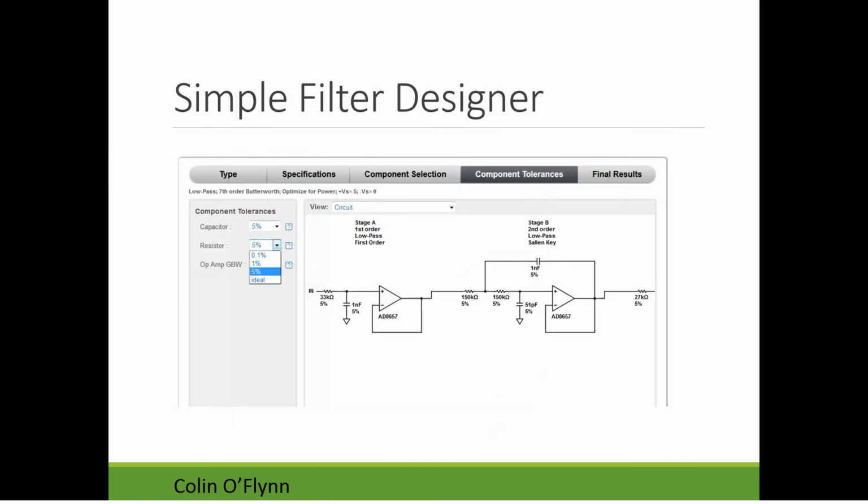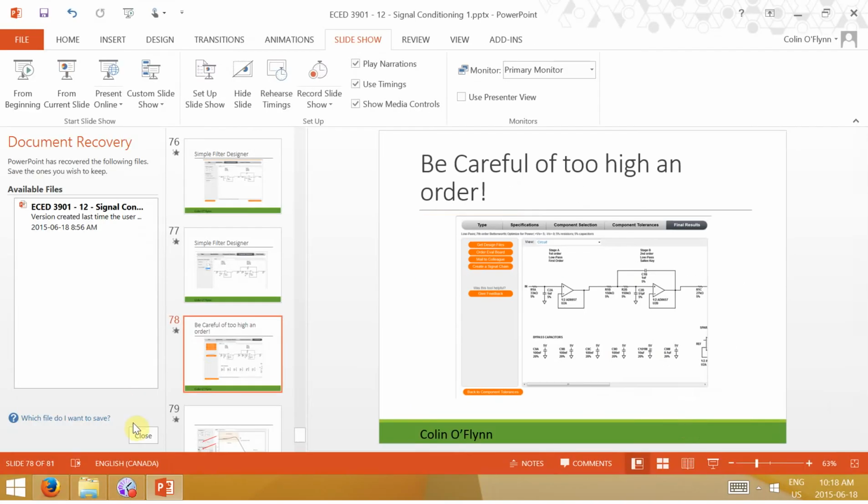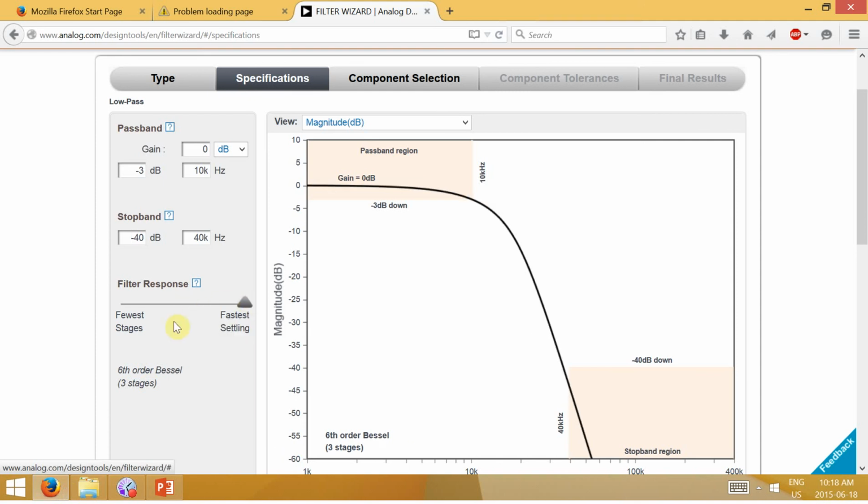The only thing to watch out for, and it'll also do this issue where you have to assign correct values to the resistor and replot, possible values to the resistor. The only issue is that, if I give it a really tricky design, it'll create this super complicated filter. So it tells you, right when you're doing this stuff here, at the bottom how many stages are in the system. This is a 3-stage design. The more stages basically means you need more op amps.